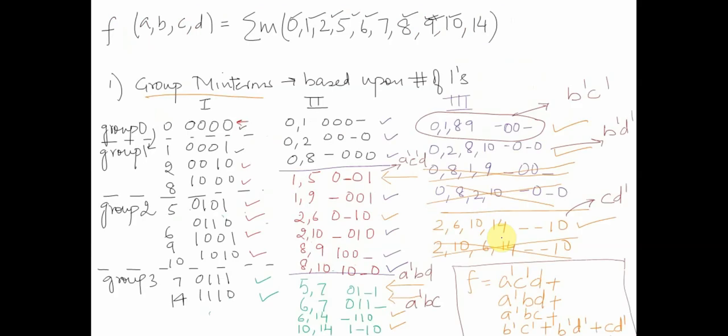So just to recap, what we did in the Quine-McCluskey method is a grouping. We figured out consecutive entries with only one digit being different, and with that we were able to reduce the entire function into a set of six expressions, and we created a circuit of those six expressions. Now this expression is definitely a minimized version of the initial minterm expression, where we had 10 terms. Eventually we obtained a circuit with only six terms, with fewer literals in each term. But this is not the most minimized circuit possible.